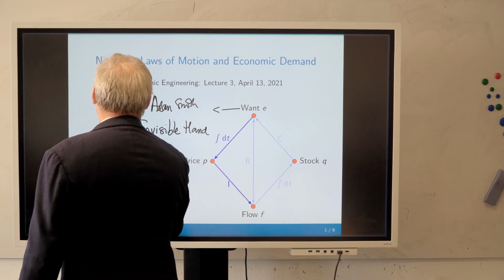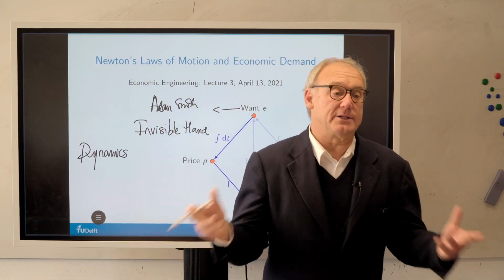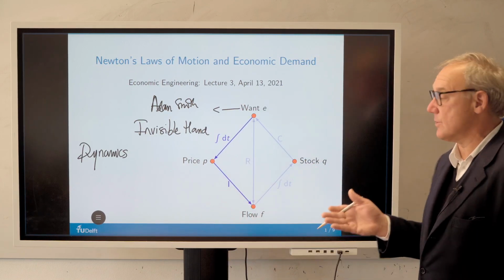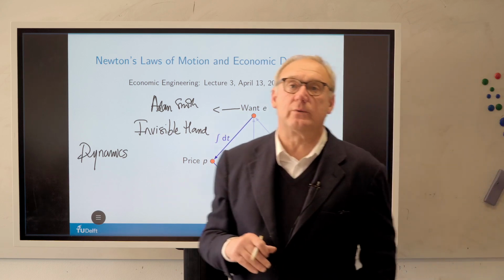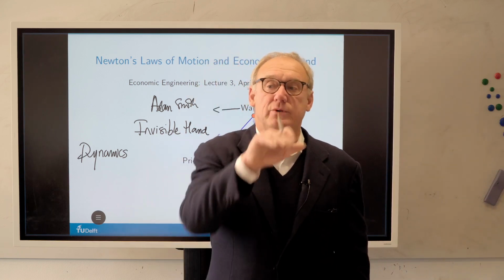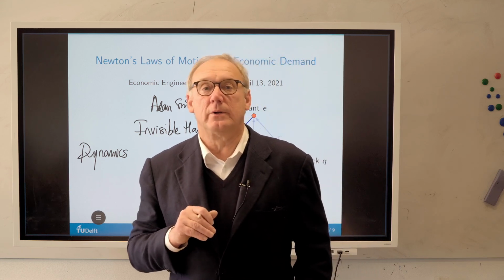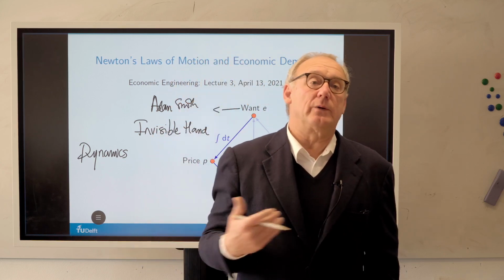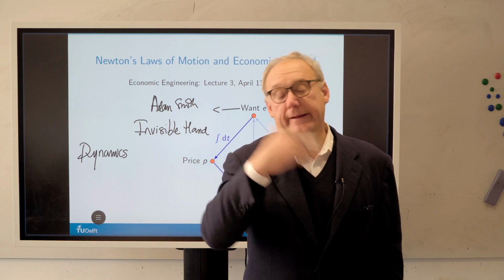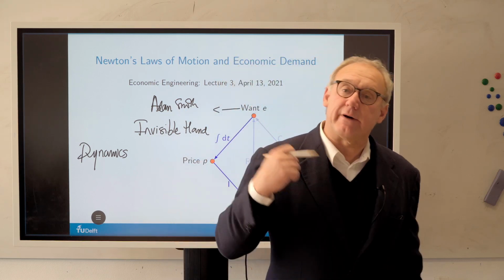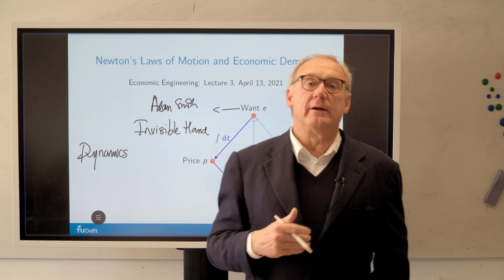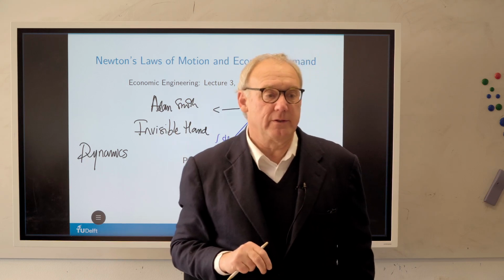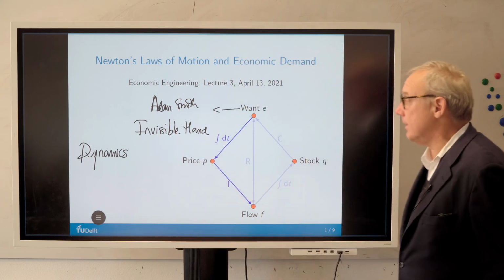With this dynamics, we can build systems, LTI systems, this system, that system, and we can start doing real control, because what is control? That's influencing the way things move to equilibrium, and at the same time possibly influencing the equilibrium state where you get to. So your controllers will try to go to the equilibrium state, and you make some PID controller, you make sure you have enough I action so you get there, and then you have enough D action and proportional action, so you can control the transient, how you get to the equilibrium state. But for that, you will need a model.